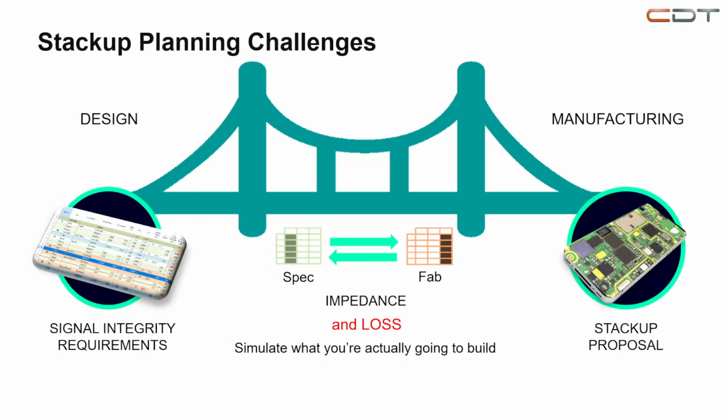So let's talk about how ZPlanner acts as the ultimate connector between design and manufacturing. The big challenge in PCB design, the biggest one, is ensuring that what you simulate is exactly what you will get in the result, what gets produced. Traditionally, this means an endless back and forth exchange of information with the fabrication house about impedances, stackup details, materials, etc.